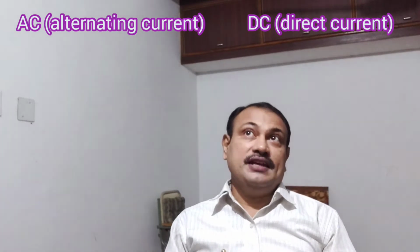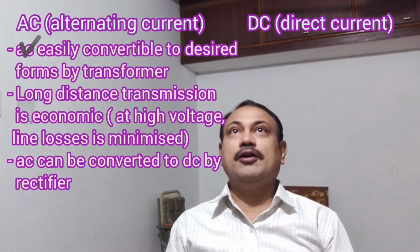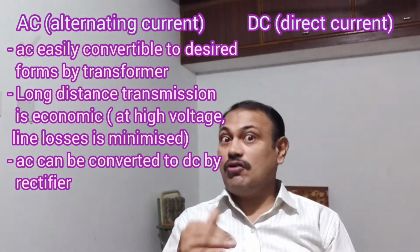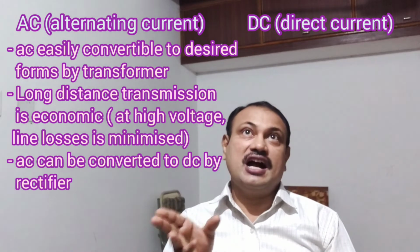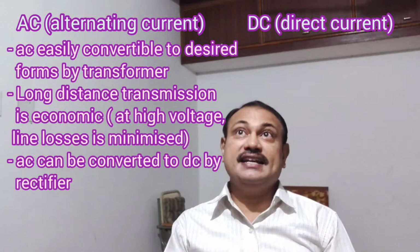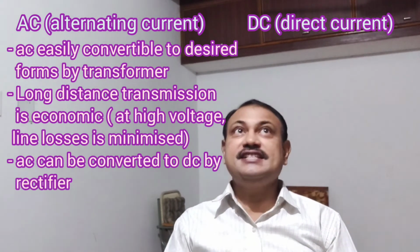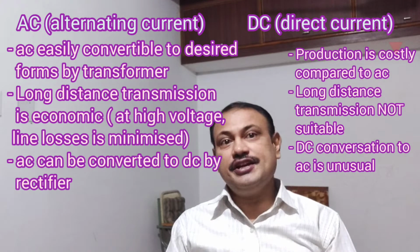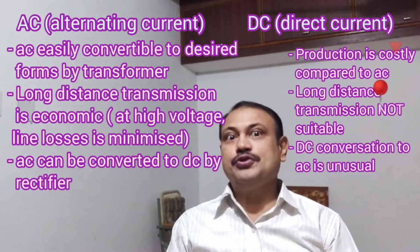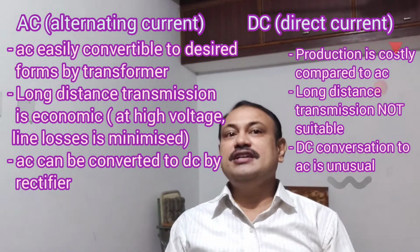Now AC can be easily converted to various desirable forms using transformers. AC transmission for long distance is also economical because at high voltage the line loss is minimized, and AC can be converted to DC by rectifiers as we have seen. But in case of DC, production is costly compared to AC, and long distance transmission is also not suitable for DC. DC conversion to AC is unusual.